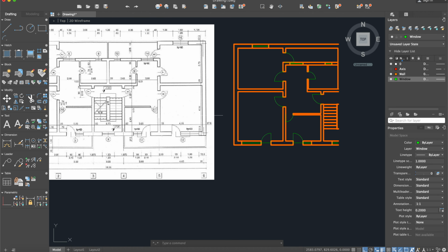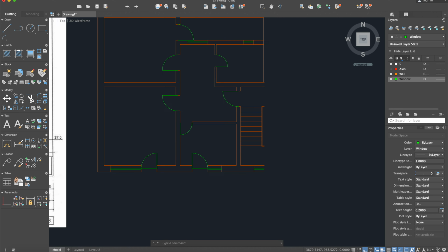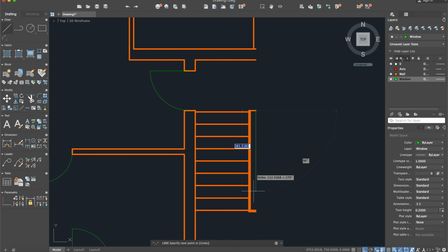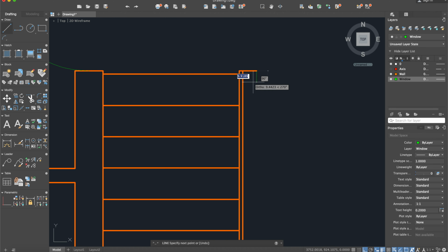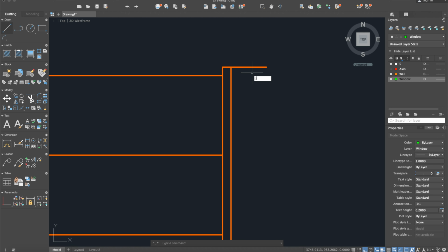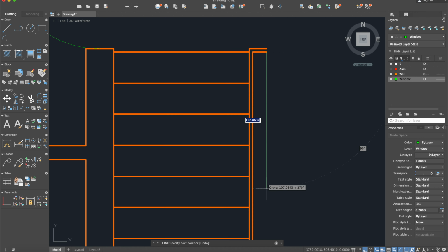And now let's do the mirror line. It's so important. Let me show you how it will look. Let's say this one will be the mirror line. It doesn't matter too much. Oh, here I forgot to put this. Offset 3, fillet radius 0. Yes, and the mirror line will be right here.